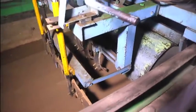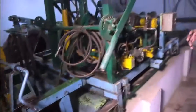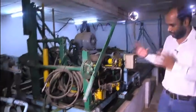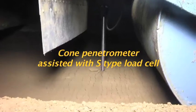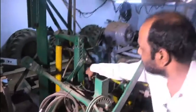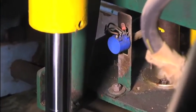And to know the compaction level of soil, we have made an instrumentation on this soil bin. With the help of the cone penetrometer, we are measuring the strength of soil. This cone penetrometer is assisted with an S-type load cell. There is a potentiometer. With the help of this potentiometer, we are measuring the penetration depth of soil.